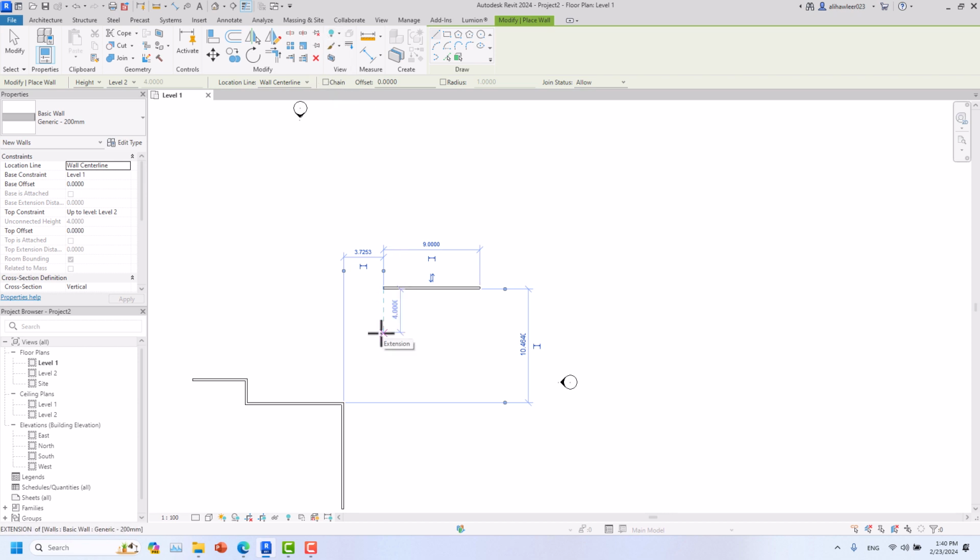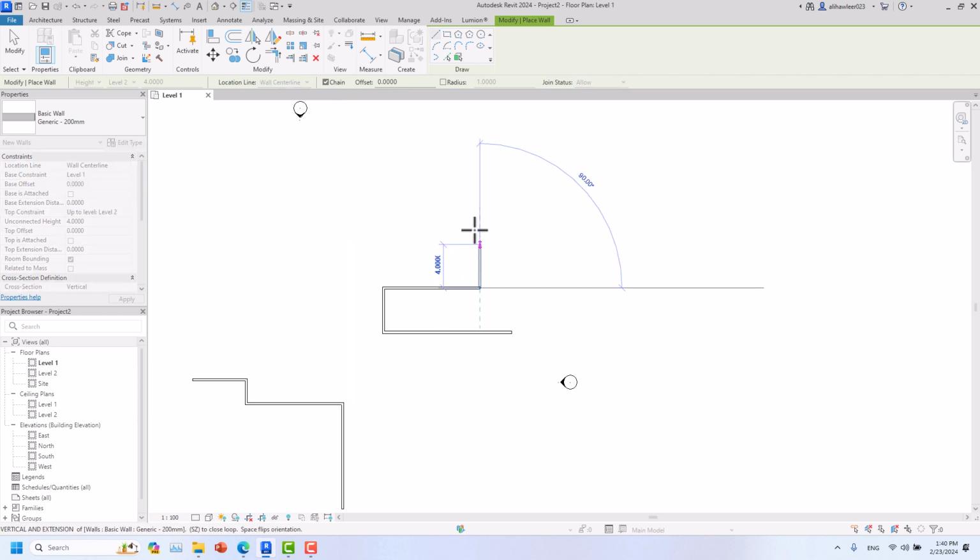So I have to come to here and create something like this, let's say, and click, and it goes out from the command, and click if I connect, and it goes out from the command. But meanwhile, if you activate the chain and just click and click, it's connecting without going out from this connection. If I escape, it goes out from the connection but not from the command, okay.